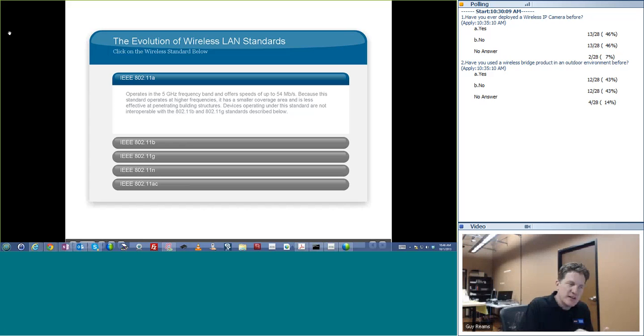So the question doesn't become a matter of bandwidth. The question becomes a matter of how much delay do I get when I send that real-time streaming protocol. The cameras and phones are identical in the way that they handle that type of communication. So your testing needs to be on the validity and the power of the antennas. You've got to make sure that the antennas are high enough gain and are connected with enough signal strength so that you get as little delay as possible when sending that stream across the wire. You need to worry about that first before you worry about bandwidth.